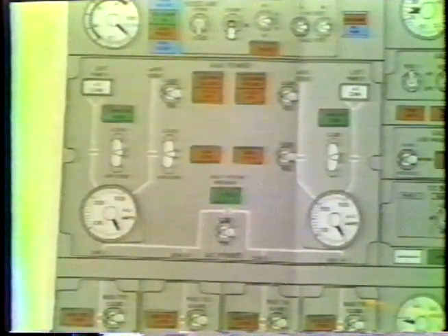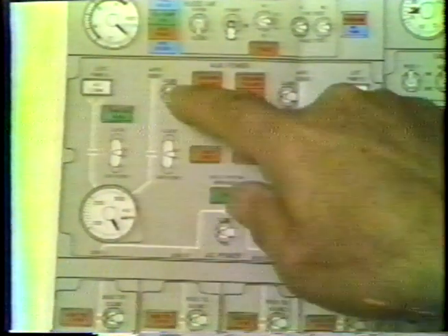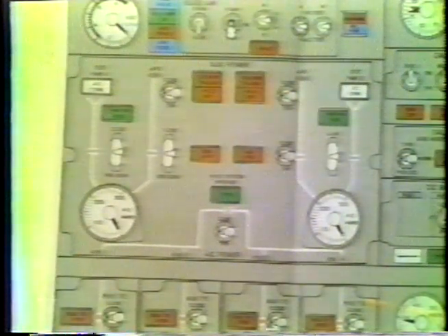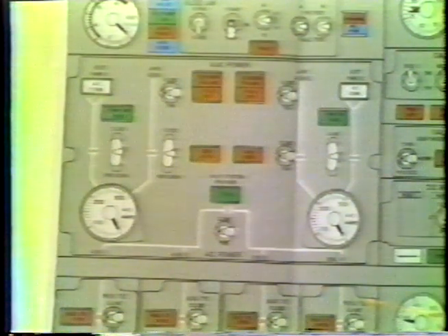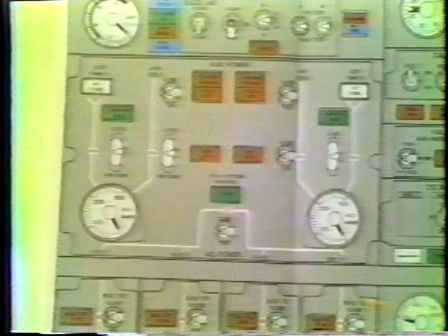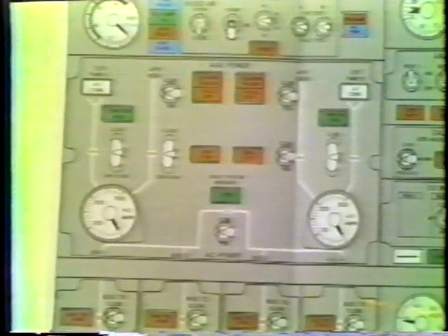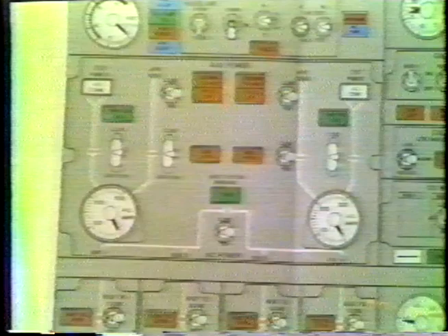At all times, ground power number 1 should be used, or APU number 1 should be used, because there is a special ground handling bus which is powered when these power sources are operated. The ground handling bus is specifically for ground operation, and there's several very important things that are on that ground handling bus.